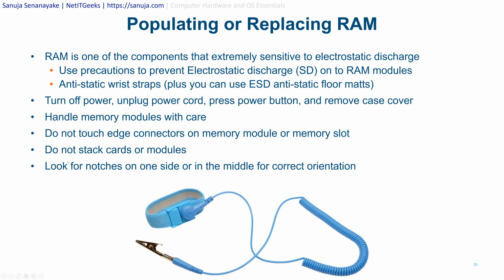That is a bad idea. During transportation, you may stack memory modules, but it should be done according to manufacturer standards and whatever anti-static covers in between. So keep that in mind. And look for notches on the side or in the middle for correct orientation.